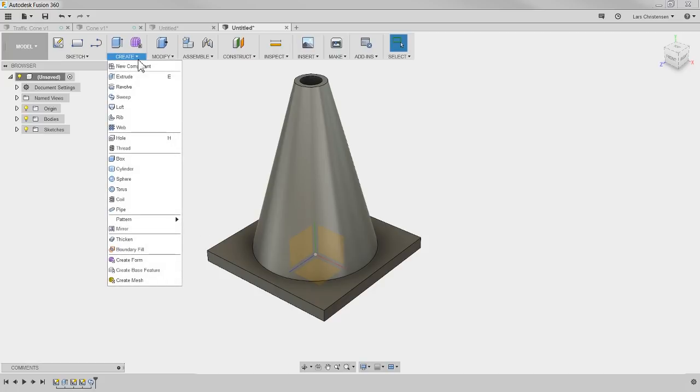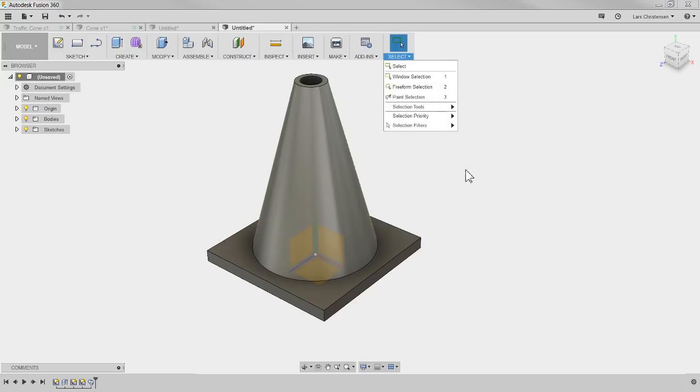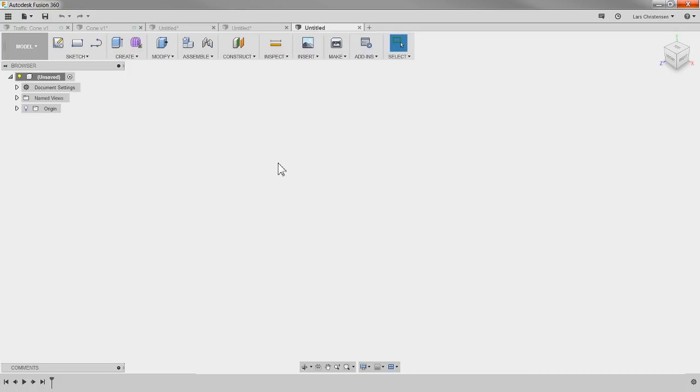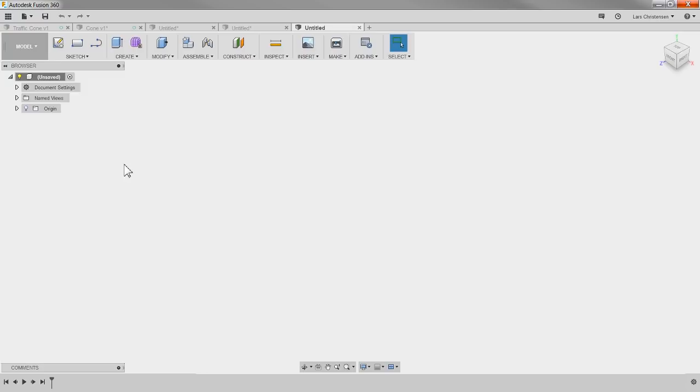The last command I want to show you is the loft command. And the loft means it's lofting between different planes or sketches. Almost think about it like a storage building. So let's open up one more design, new design. On the other ones, we started with our 300 by 300 rectangle and extruded up 25. Extruding that out 25 is definitely the easiest, like we did in the beginning here. But you could use loft here.